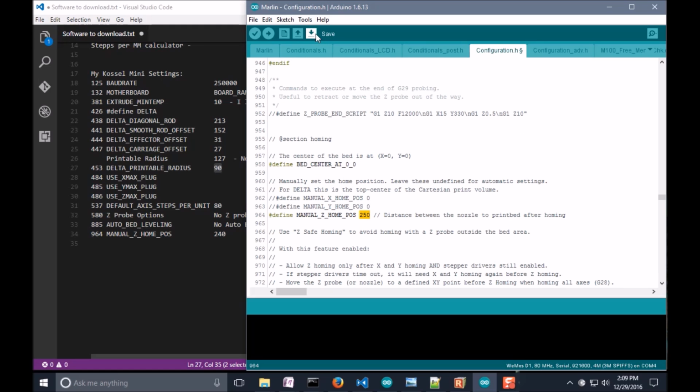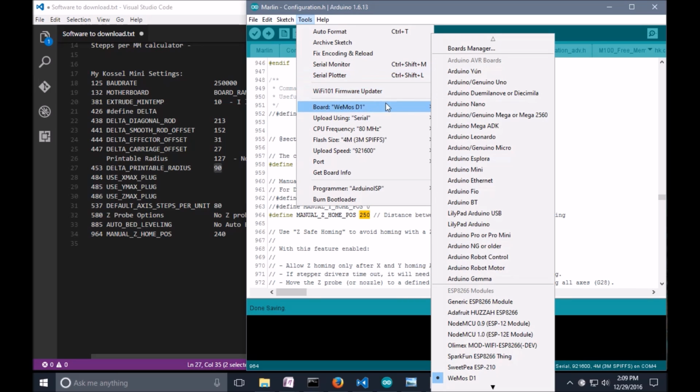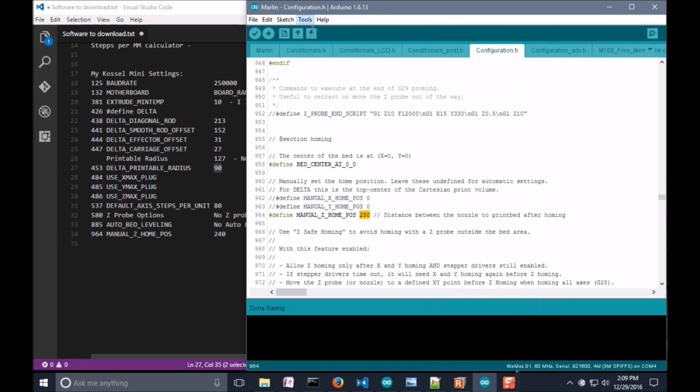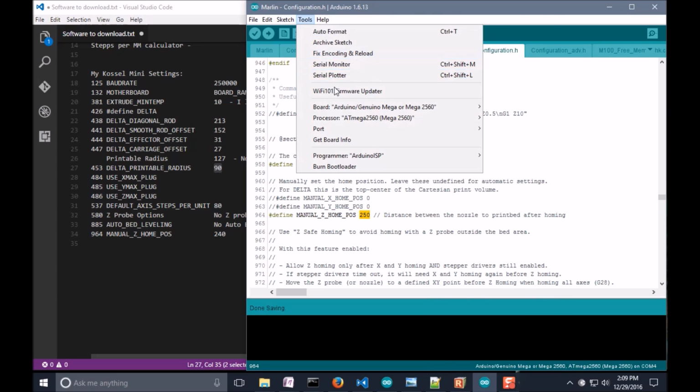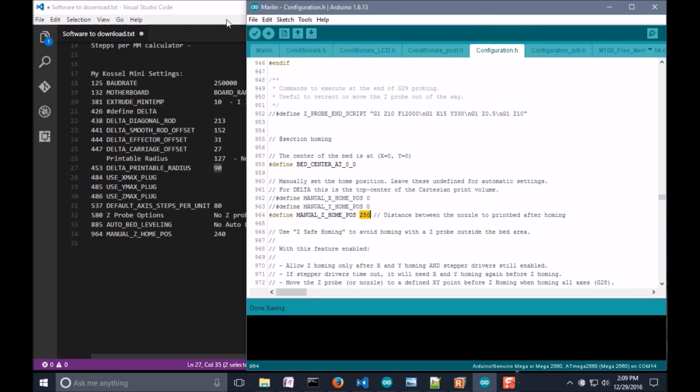So I'm going to go ahead and save this guy. I better select the right board, which is an Arduino Mega 2560, and my port is 14. Let's go ahead and upload, and this can take about 3 minutes, a couple minutes to upload.